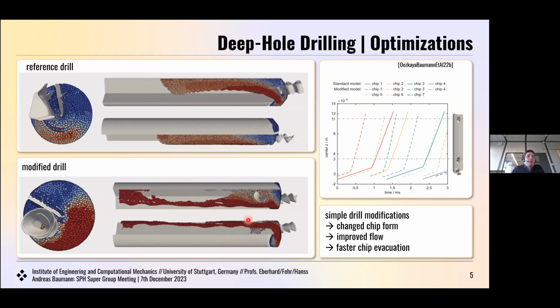We try to place them as close as possible to the cutting edge as they would come in reality from the machining process. And then we introduce them into the borehole, and once they are completely within the borehole, we set them free, and then they are governed by their equations of motion and the interaction with the fluid, and then we have the regular simulation and evacuation of the chips.